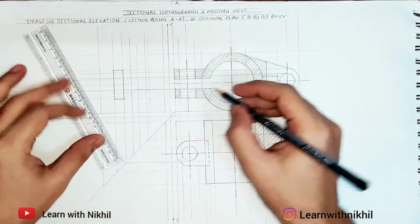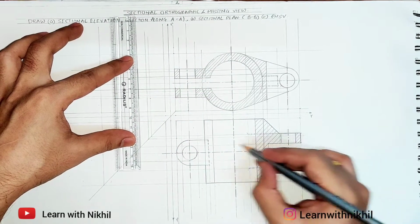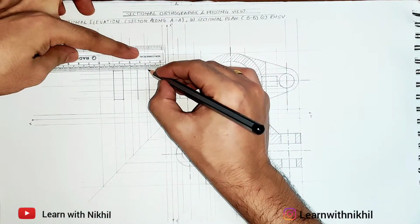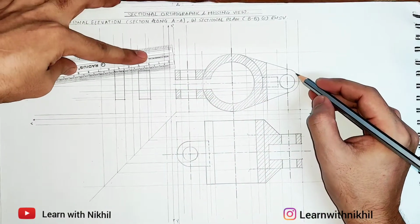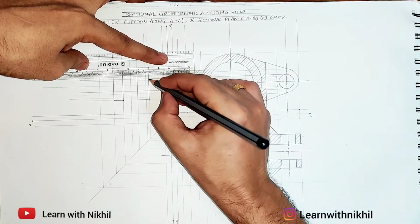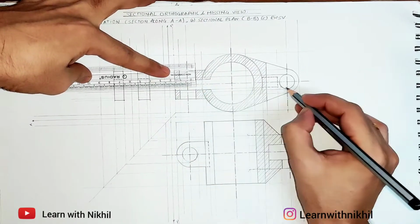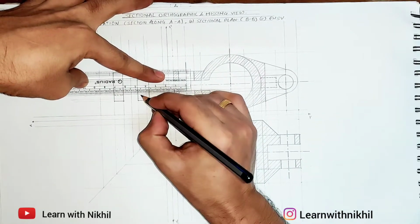It will be straight. As you can see, this is that part. Just properly see the projection lines and draw it. Now this circle is hidden. You have to draw the normal right hand side view. So this circle is hidden, so I'll draw it dotted in both the slots. Trace the projection line properly and draw it.